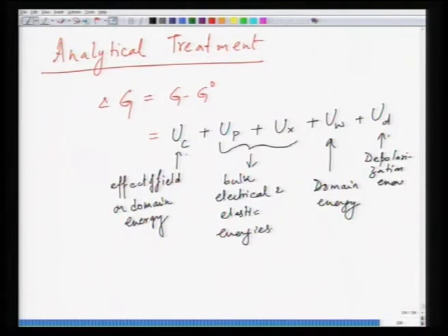Which is basically due to depolarization field. Now here the first three terms are effectively neglected in the minimization of free energy, because these three terms do not have significant influence on the domain size, because elastic and electrical energy are virtually constant, or they can be assumed to be constant for simplicity of treatment. And if you make the electric field constant, then this effect also is neglected.